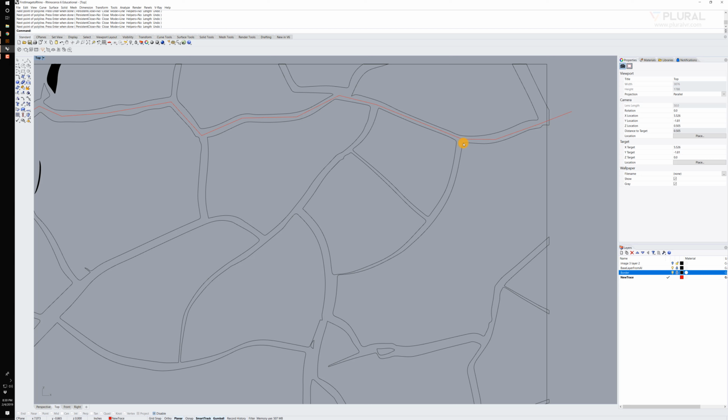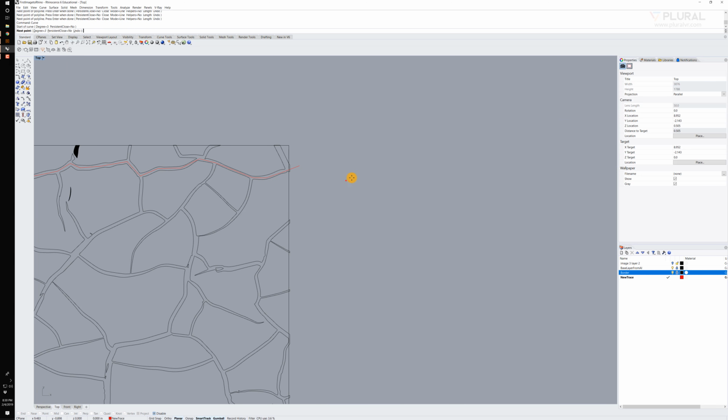Something like that. The other thing we looked at is the difference between curve and interpolated curve. So if I use a curve, I'll do that over here, I'm snapping vertices and control points, but it's averaging that curve through those vertices. If I hit enter and accept that. If I look at an interpolated curve, that's interp curve, that's the command up here, interp curve. When I click, the curve actually moves through the vertex as I click it.